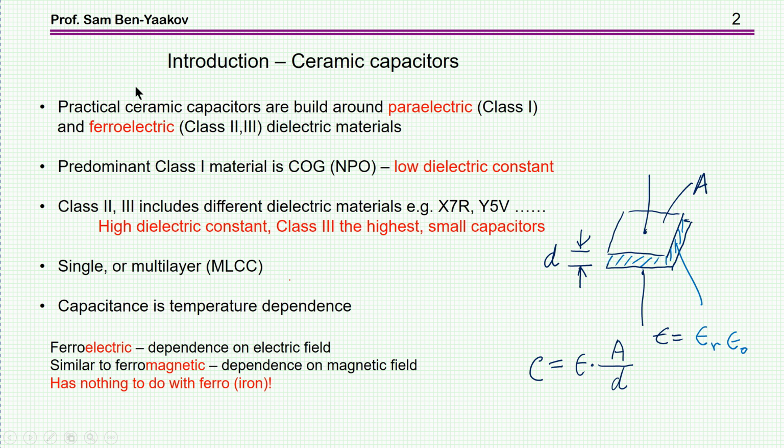Now, practical ceramic capacitors are built around either paraelectric or ferroelectric dielectric material. The paraelectric material is a dielectric which is not affected by electric field, it's not polarized. On the other hand, the ferroelectric material is a dielectric that is polarized by an electric field.